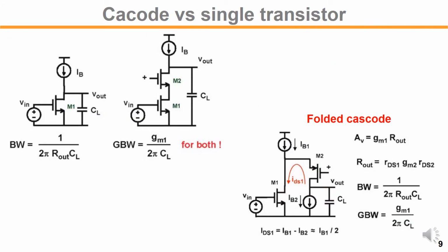Now the high frequency response for the cascode and single transistor circuit. We will see the difference. At mid-band frequency, the impedance from the capacitance would be small compared to RO from the transistor output. For the input variation, the current through the transistor will be gm Vin.